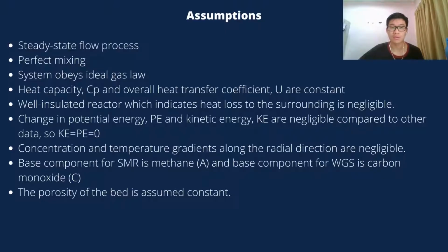Fifth, this is a well-insulated reactor, so heat loss to the surroundings is negligible. Sixth, change in potential energy and kinetic energy are negligible compared to other data. Seventh, concentration and temperature gradient along the radial direction are negligible. Eighth, the base component for SMR is methane and the base component for water gas shift is carbon monoxide. And the last is the porosity of the bed is assumed constant.